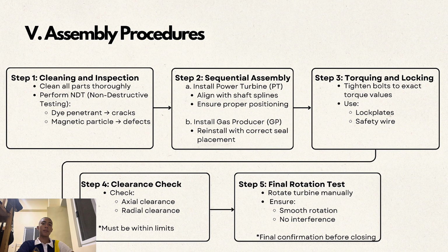With the rotors in place, we install the stationary beams. Position the first stage nozzle. This component faces the highest thermal stress. Ensure the mounting lugs are not cracked.